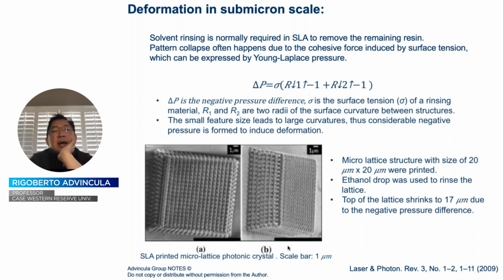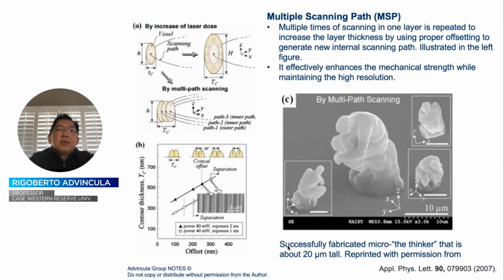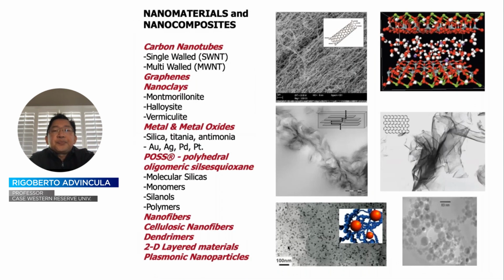where patterning then is again based on the mechanical control of that voxelization in the Z scale. On the other hand, multi-scanning paths, different types of feedback control can be used to optimize the projection of this light such that very high resolution is achieved, and these are really old images. You can see the literature going back to 2007 or even the 1990s, where 3D printing basically is represented at the hundreds of nanometer scale as shown here.